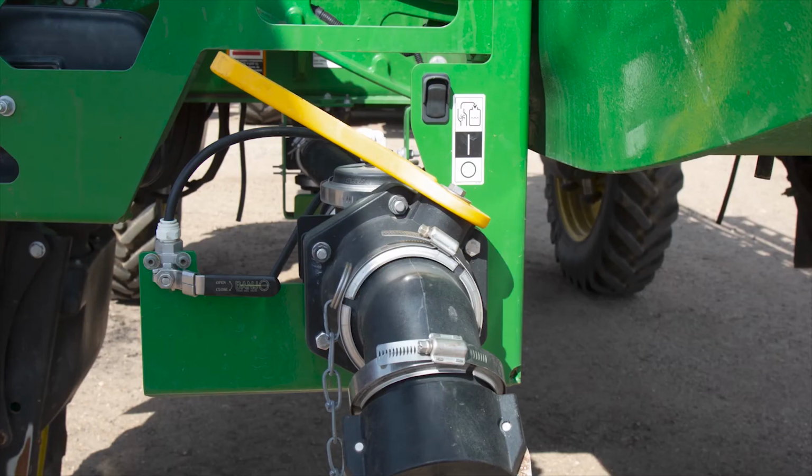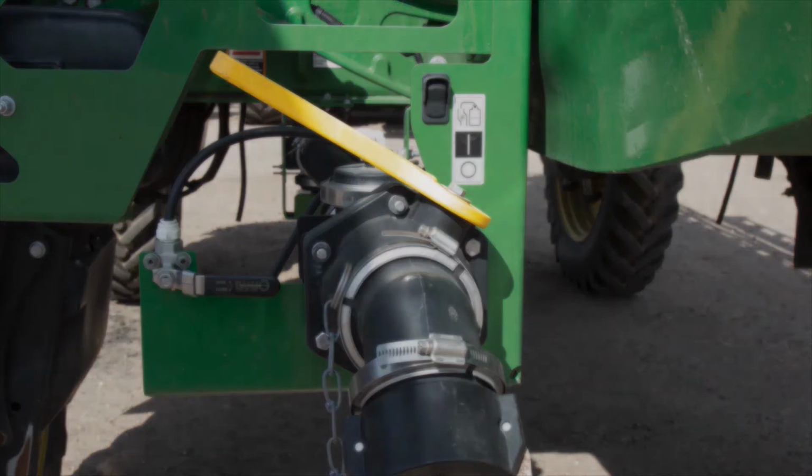When we look at the front of our machine, one of the options that we have is to add a front fill line option. The front fill option is a 3-inch fill, and it does have a couple features that we're going to call out. So first off, it's got the yellow banjo valve there. That's just an on-off valve, isolating the machine from whatever you're nursing the sprayer with. On the left side, there's a black handle, and that handle is an air purge line.